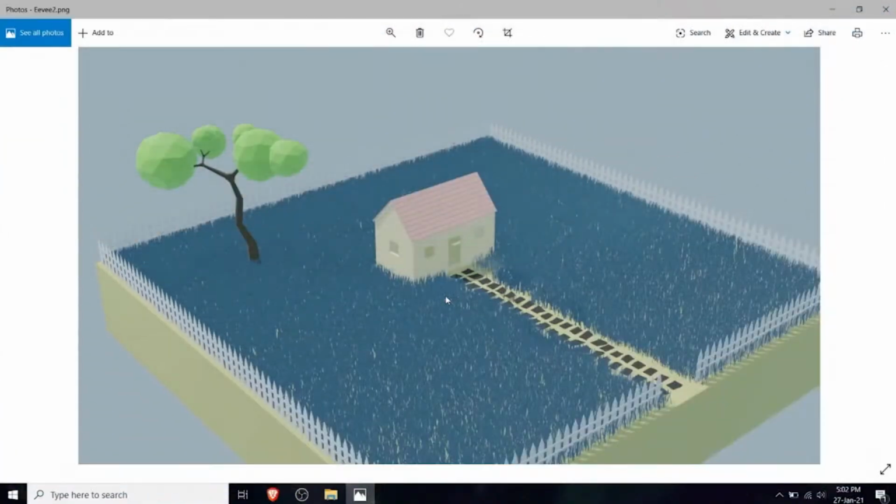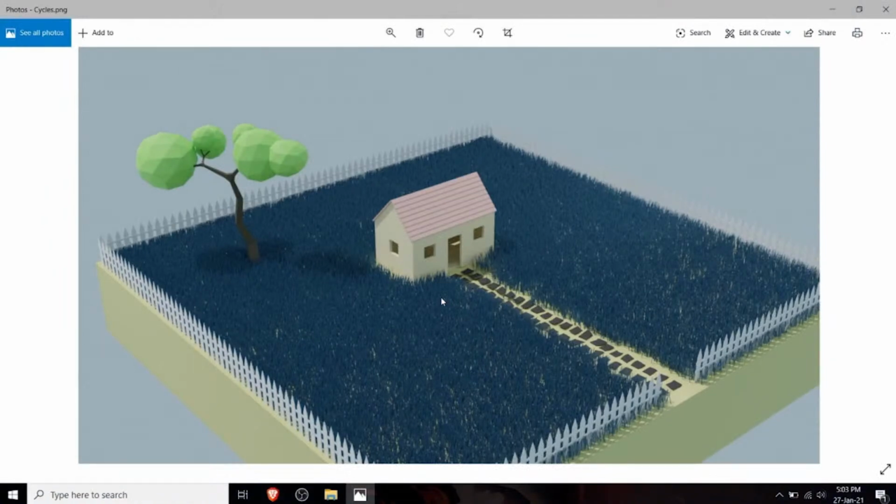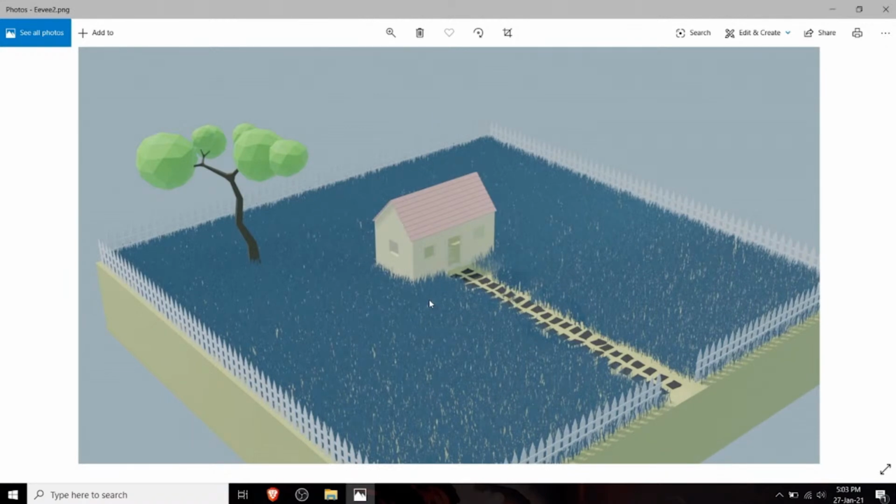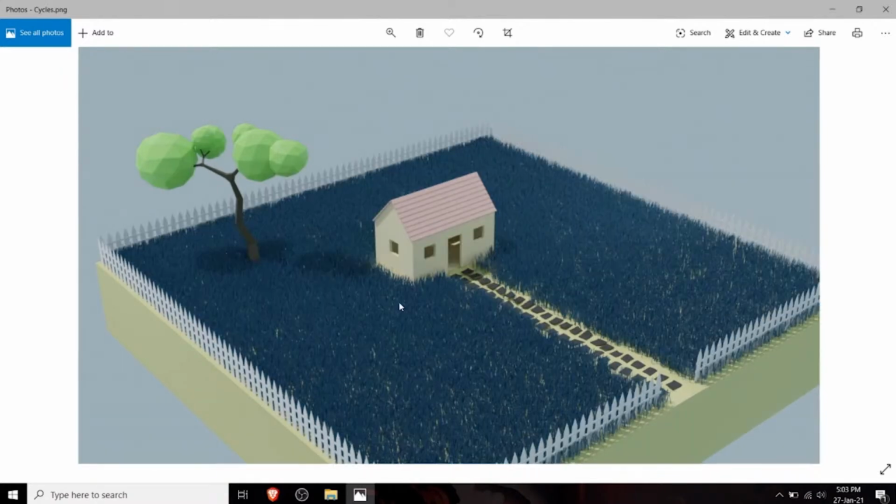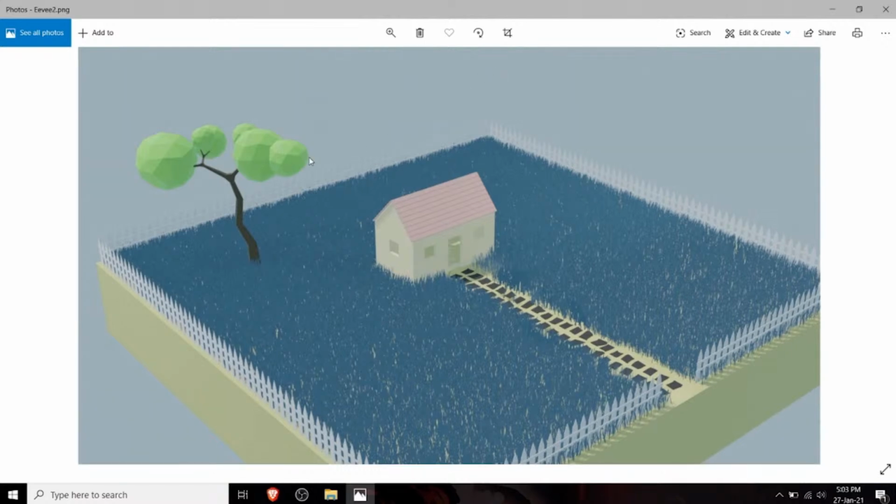I just want to talk a bit about the renders. So this one's done in Eevee, this one's in Cycles. As you can see, the Cycles render is much better. Eevee is the render engine that's usually used in game engines, so it's optimized to be done instantly. While Cycles is much slower, but it gives much better quality because Cycles has bounce lighting. Basically, when light hits an object, the light bounces again and hits another object. And it hits again another object. Usually, by the third time it hits an object, it has lost most of its energy. So if you have 3 hits, that gives pretty good quality. If it doesn't have that, when the light comes and hits, that's the only thing it renders, nothing extra.